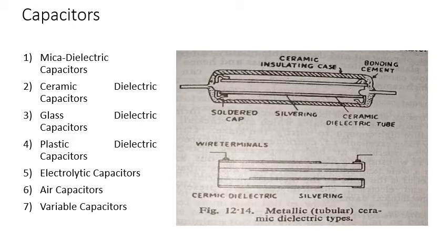The silver mica plate capacitor has a better temperature coefficient when compared to the stacked plate type. Both types exhibit slight non-cyclic capacitance shifts during temperature variation, yielding a non-linear temperature and capacitance characteristic. The power factor of mica is approximately 0.0003 at 1 megahertz, but can be as low as 0.00005 when very dry, and the permittivity is around 7.